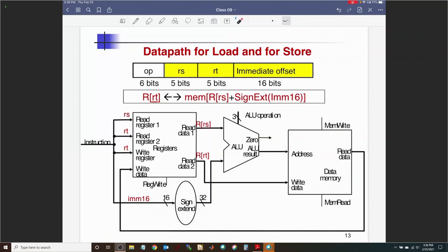Because when you do an ALU operation, for example, you're trying to add this guy, the base address will have something in the memory which is 32-bit long, so that goes over here. So it needs to get added with something that is also 32-bit. So you take in the 16, make it into 32, and then you do the addition using the ALU.